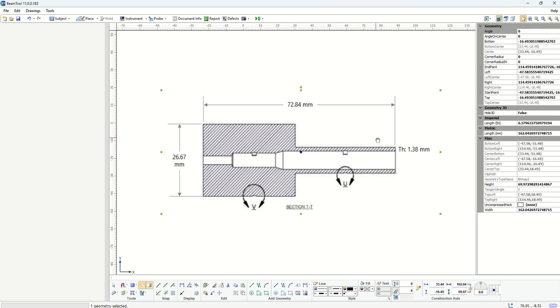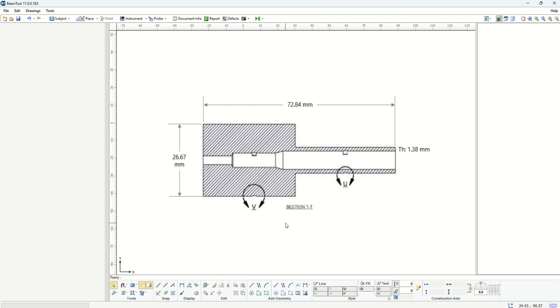So basically the idea is that we design a technique that lets the sound go through this thin section and then this thicker section, and be sensitive in detecting any surface defect or surface breaking flaws that are simulated by notches here. Okay, so the first thing is obviously we need to prepare a drawing of this piece that needs to be to its scale.